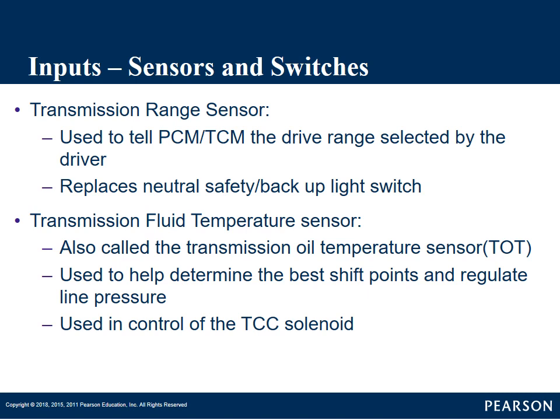It's going to replace the neutral safety switch and the backup light switch. A neutral safety switch doesn't allow you to start the vehicle unless it's in park or neutral. That way, if you had it in reverse or drive and started it up, the vehicle's going to try and take off and move before you're ready. So that is the purpose of a neutral safety switch. You can only start that engine whether it's in park or neutral.